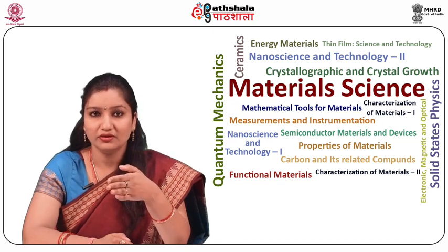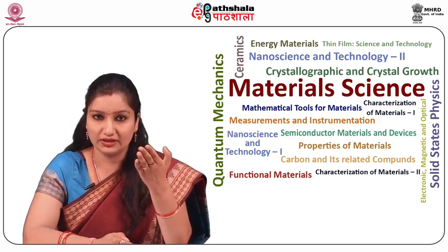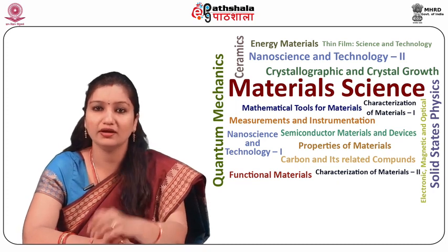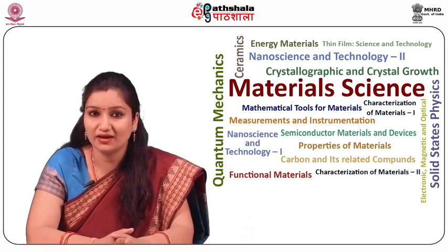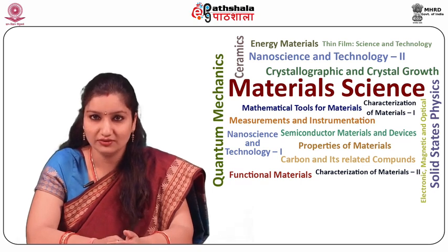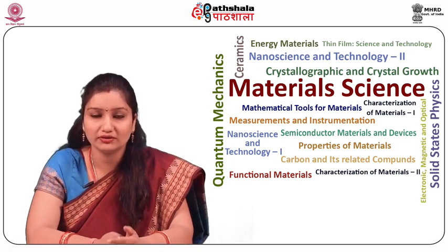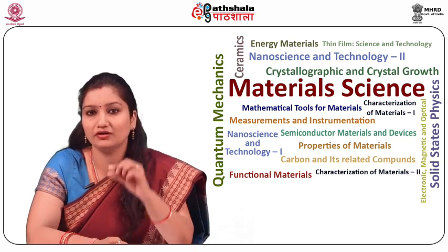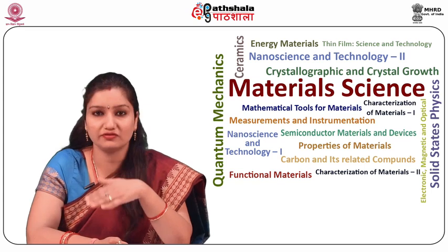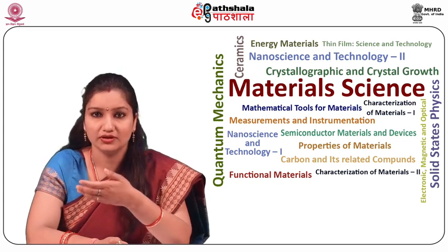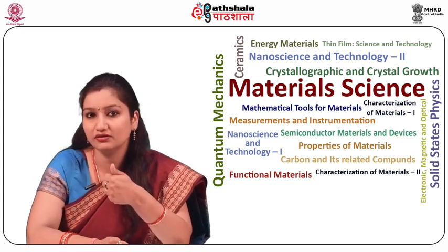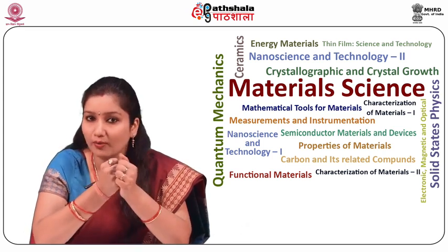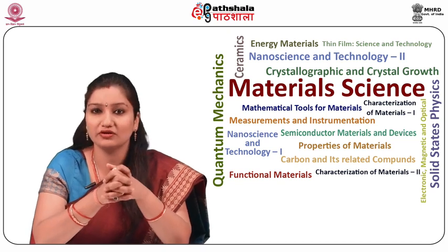The relation is given by KC equals K divided by S naught, where K is the work of the fracture and S naught is the cross-sectional area of the specimen at the notch. Impact strength is indicative of the toughness of the material, that is, the ability of the material to absorb energy during plastic deformation.